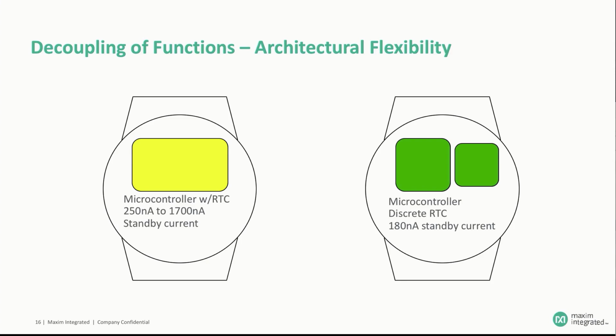The idea behind PMICs is to integrate as much power management into a single device as possible. PMICs, as one can imagine, carry the quiescent current payload of all the functions that they utilize. So you are adding up the quiescent currents of the switcher, battery management circuit, etc. While many of those functions can be turned off, PMICs will always have a greater payload.